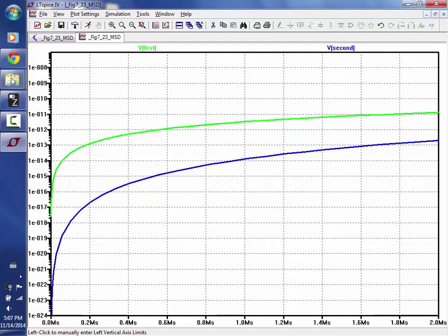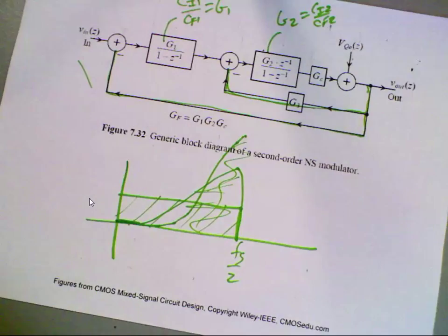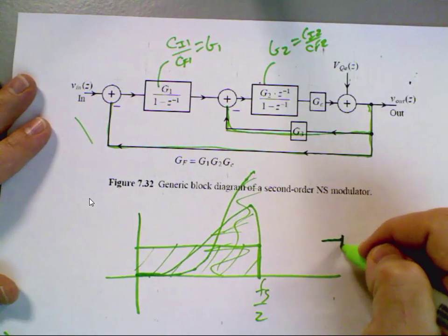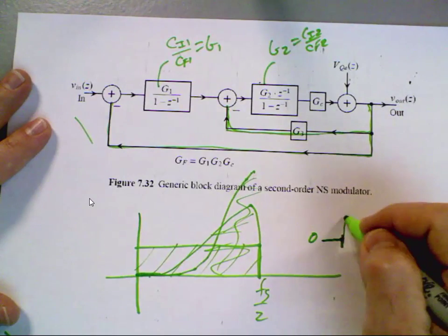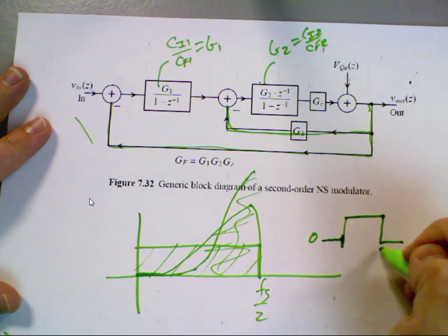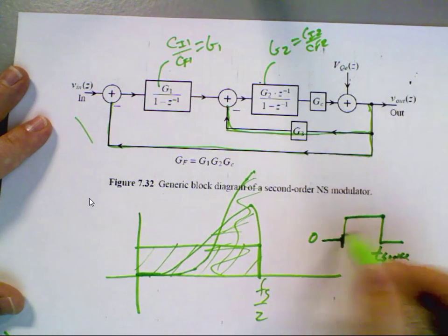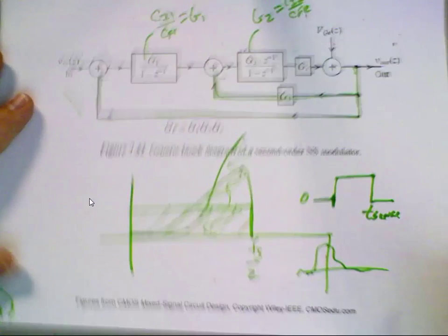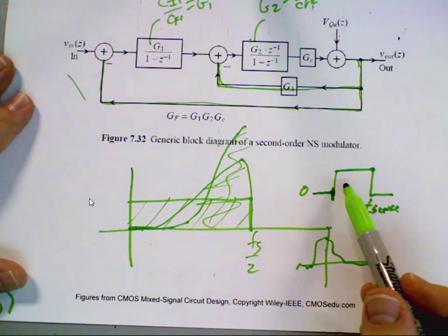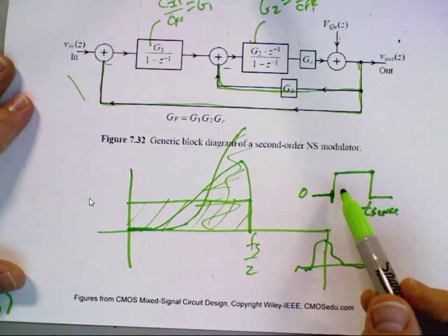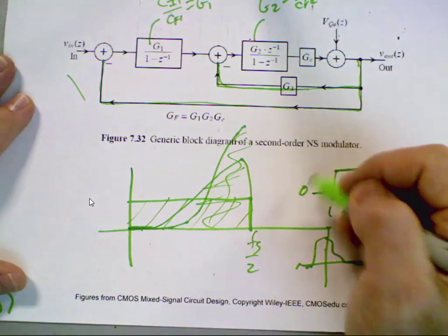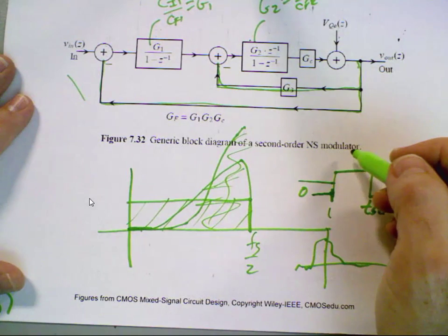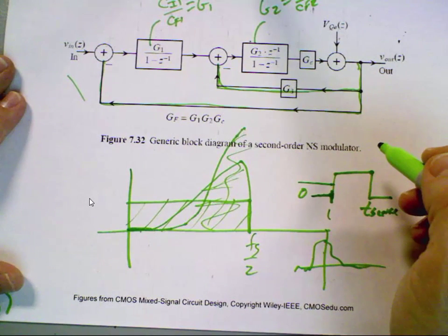What I'm saying is, if you look at sensing like this, where it comes up, and I start sensing right here, you could think I have 0 input on my sensing, and it comes up and goes over. In the time domain this corresponds to sensing like a pulse, like a sinc function. So in my mind, if you're using second order noise shaping, this could work better. However, if before you start sensing you let your sensing circuit run, then I think it'll behave like a DC circuit, and you won't see any difference between first order and second order. Did that make any sense whatsoever?